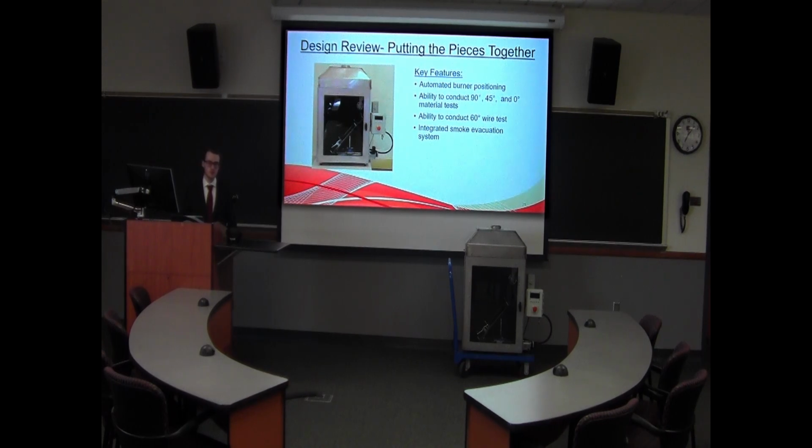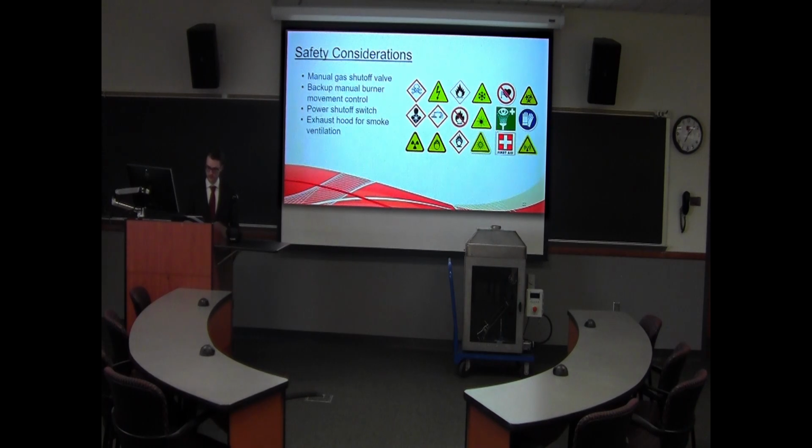Due to the absence of a smoke hood in the Kodiak laboratory facility, a smoke evacuation system has been designed that integrates with the top of the cabinet. The flammability testing cabinet necessitates the usage of a high-temperature flame and flammable gases, which raised several safety concerns we had to address during the design process. To reduce the risk of an out-of-control flame, a manual gas shutoff valve was placed in the gas supply system to quickly shut off gas to the burner in the event of an out-of-control burn.